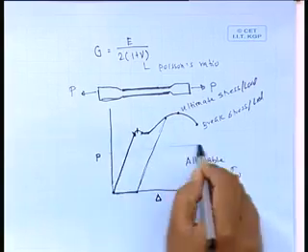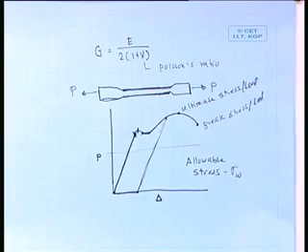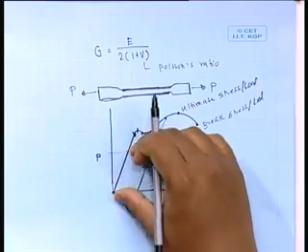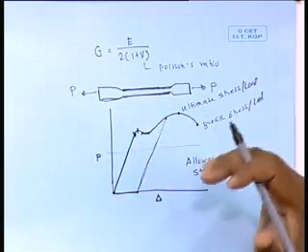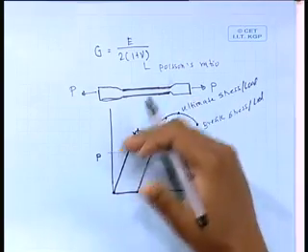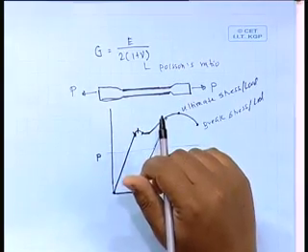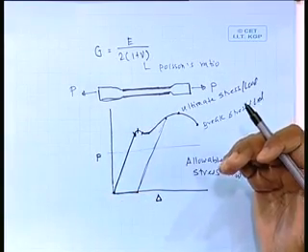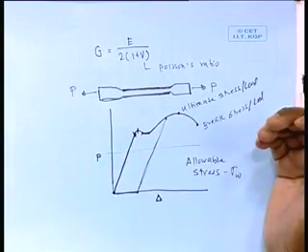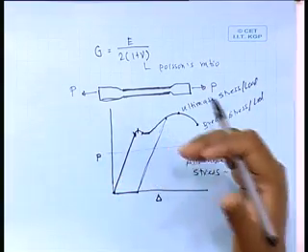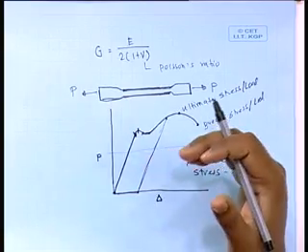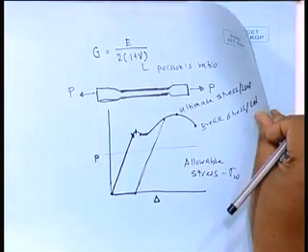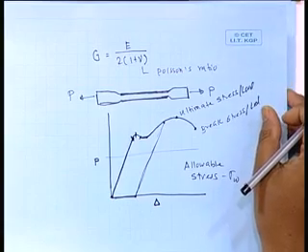So, if we come back here, this divided by some factor, so normally it will be somewhere here. So, our design limit will always be within the linear range, keeping some safety factor in our hand, because any load we calculate may not be ultimate, there might be some unseen forces. So, that part we have to keep in our hand, so that the risk of failure will be as minimum as possible.